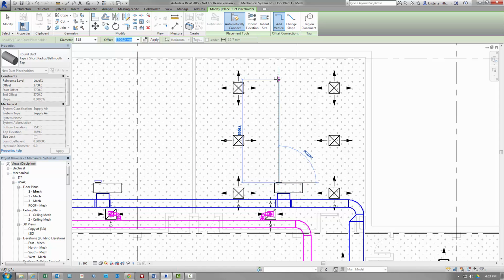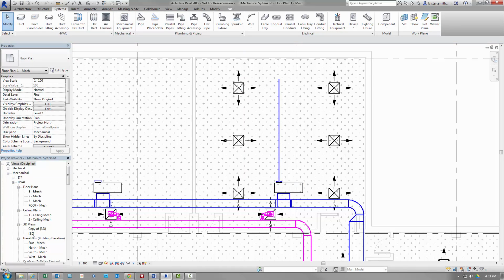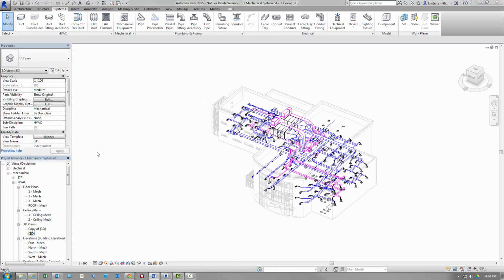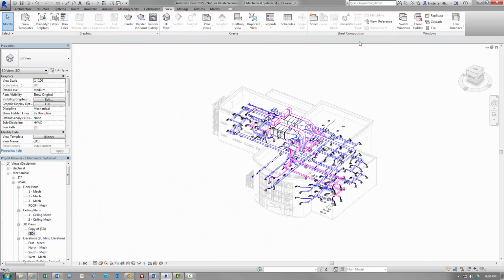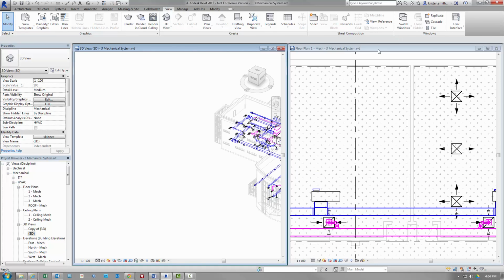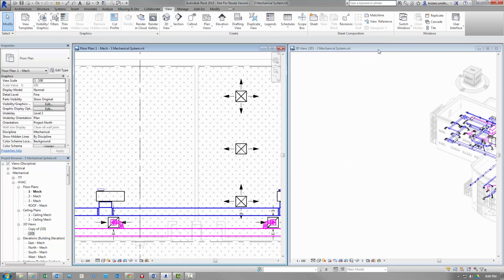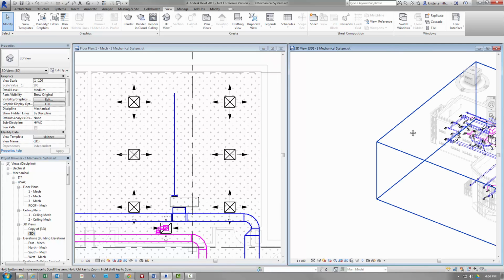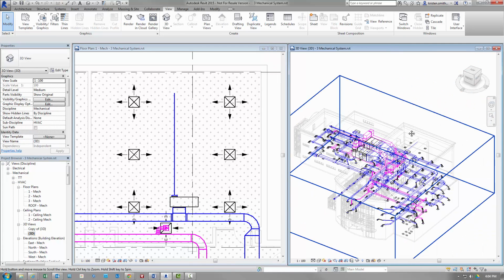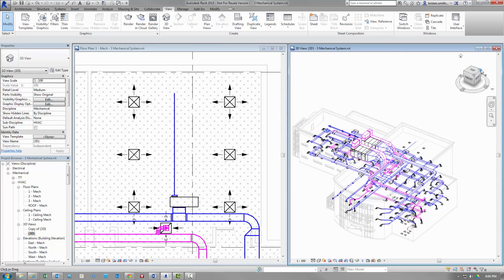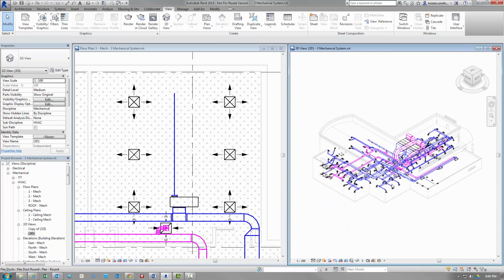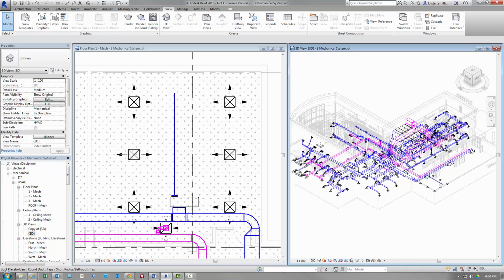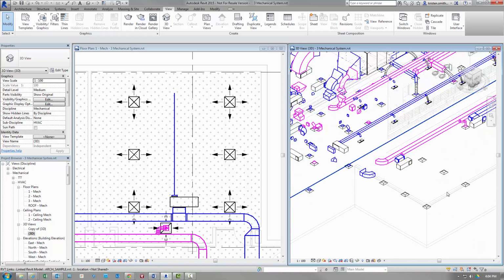Select the placeholder duct and draw in some duct. This will automatically select the last duct system that you previously drew. Since the placeholders will not place all of the fittings or actual sized duct in the model, manipulating the single line geometry is easy as there are no connections made. A schematic layout is not only a 2D sketch, but also contains 3D relationships without connectors. Therefore, it is especially convenient to open a 3D view as we add the remaining duct placeholders.